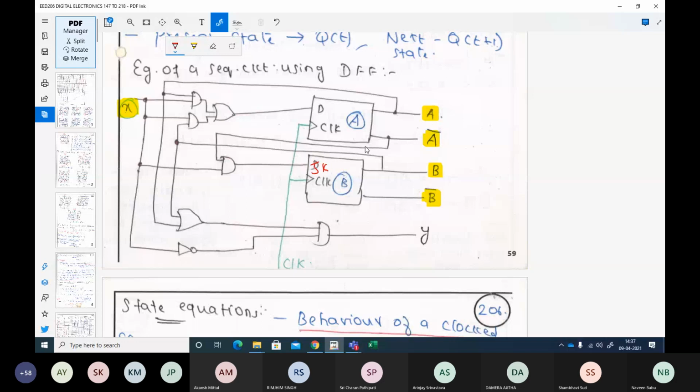So, and the other outputs. Y is an output here. So this is an input, this is an output. We do not really require these outputs, but they are required for our understanding because they give us the next state outputs from these flip-flops. At the same time, there are more inputs here. There is an input to this flip-flop, which is nothing but the present state input. So to summarize, what we need is input, output, present state, and next state.